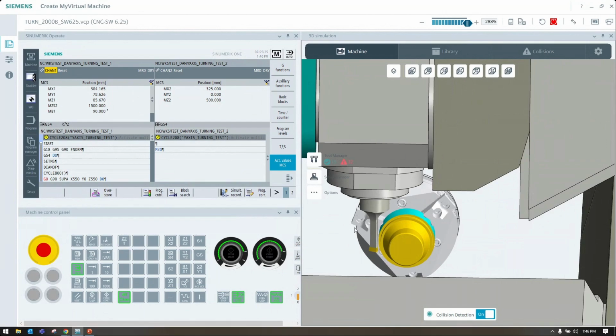So we're going to specifically apply it on smaller diameter parts, we're saying. Yeah, within fitting within the size of the chuck and the Y-axis travel is the big thing there. As you get to, I would say, 10 inches, I think you're losing out on that. And if you're getting that big, you probably have a different strategy of turning in that case anyway.